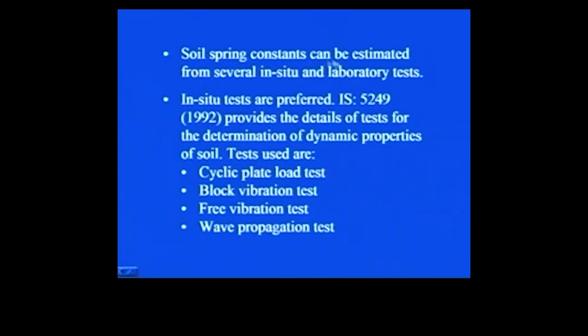The soil spring constant can be estimated from several in situ and lab tests. In situ tests are conducted in the field, however, lab tests, as the name suggests, are conducted in the laboratory. In situ tests are preferred because they represent the real situation existing in the field, and the exact condition that the soil foundation system will be subjected to.